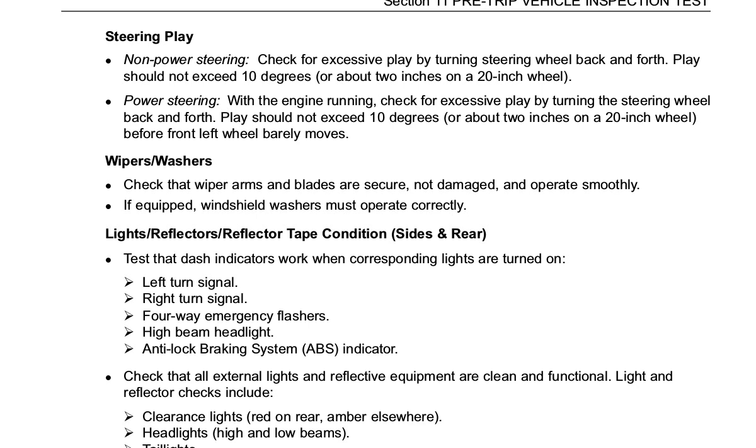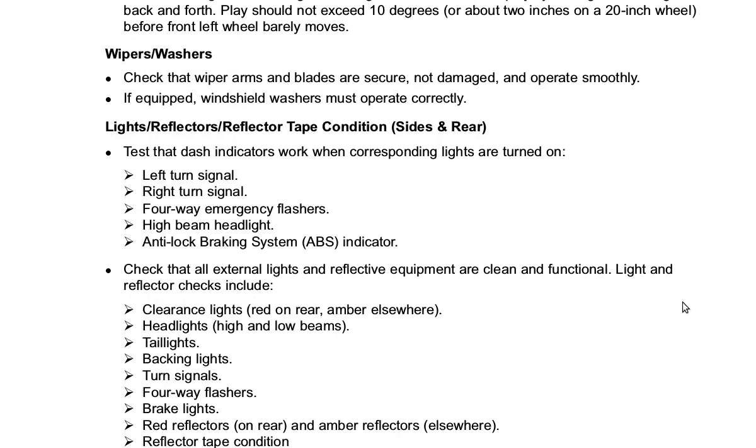Lights, reflectors, reflector tape condition, sides and rear. Test that the dash indicators work when the corresponding lights are turned on: left turn signal, right turn signal, 4-way emergency flashers, high beam headlight, anti-lock braking system, ABS indicator.